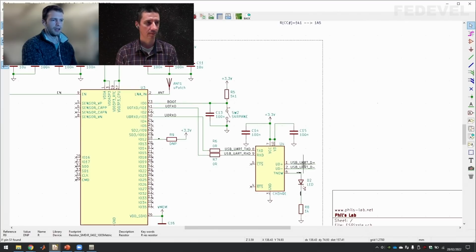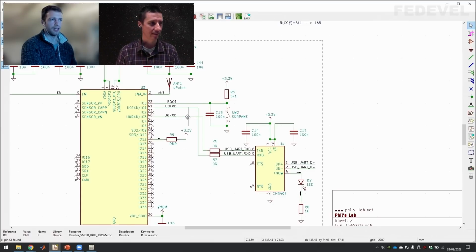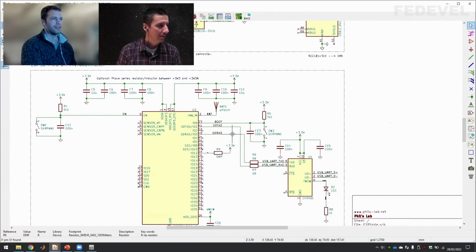And I believe you can download for the Arduino IDE a board support package for ESP32 microcontrollers. So it can be flashed, or you upload a certain bootloader to your ESP32. But you can't really debug the chip. Or you can debug it step by step through UART. If you had the JTAG signals exposed, then you could set breakpoints and all of that stuff. But I haven't for the moment. Just to see if I can even get the basics running and then slowly move in.